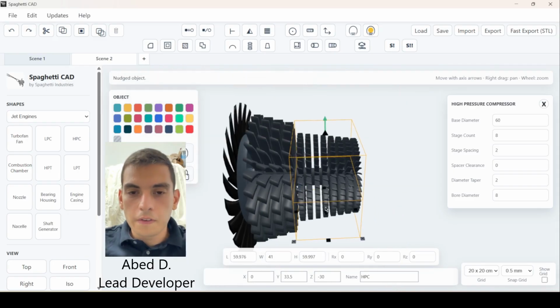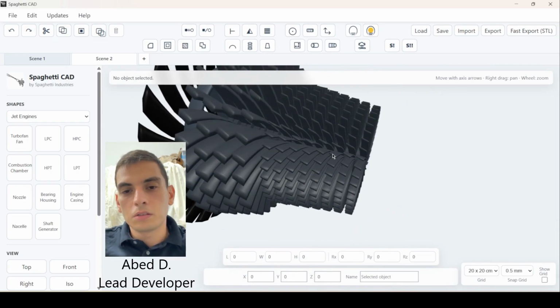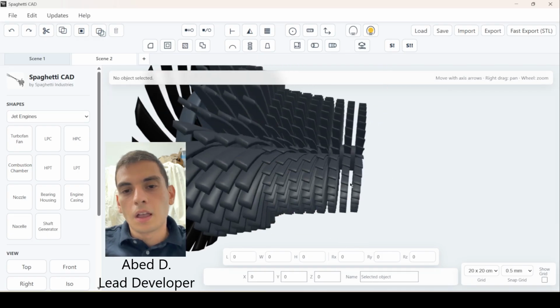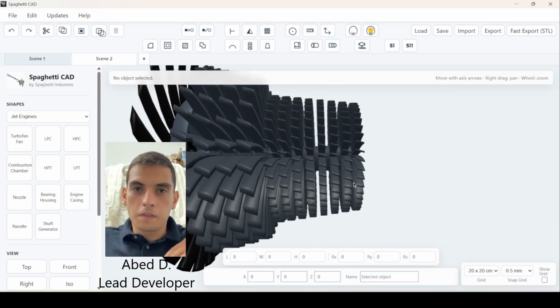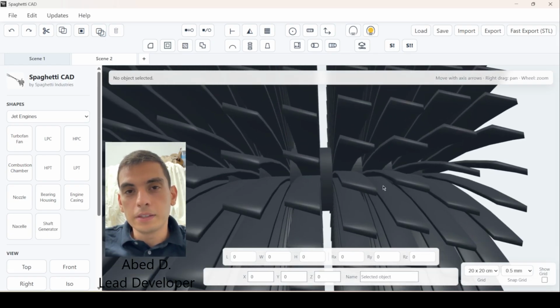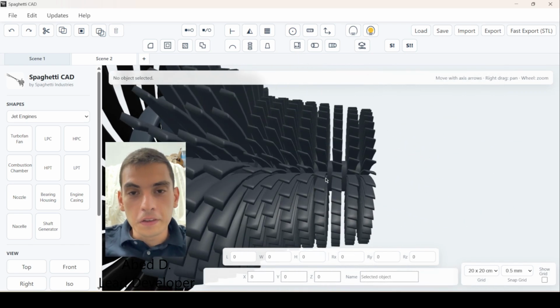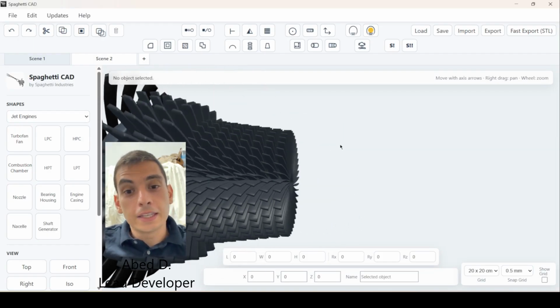Now, as you know, when you 3D print things and assemble them, you typically want to have parts that are a little bit shorter than what they're supposed to be so that everything fits together. So if you print it like this with the 2 millimeter spacing, you're going to have an issue. Depending on the tolerances of your machine, you're going to have to decrease this value a little bit. I said this is not easy.